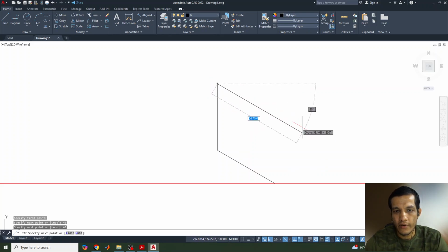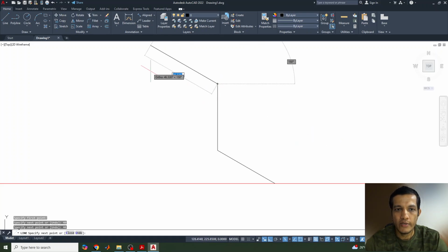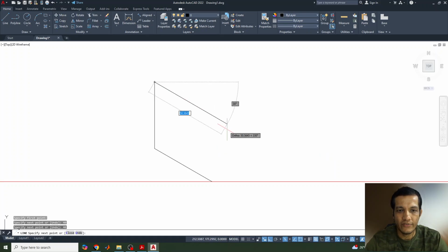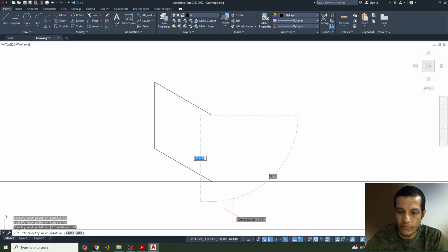Now if I keep my cursor this side, automatically it is coming in this way. If I go that side, it will go that way. It won't go to the right side or any other sides, because we have selected ISO left only. Again, an angle also you can see that if I click on the tab angle, you can see angle 30 degree. I'll show you that measurement also, in the last 40. Again, come down for 40. Now you can enter it.